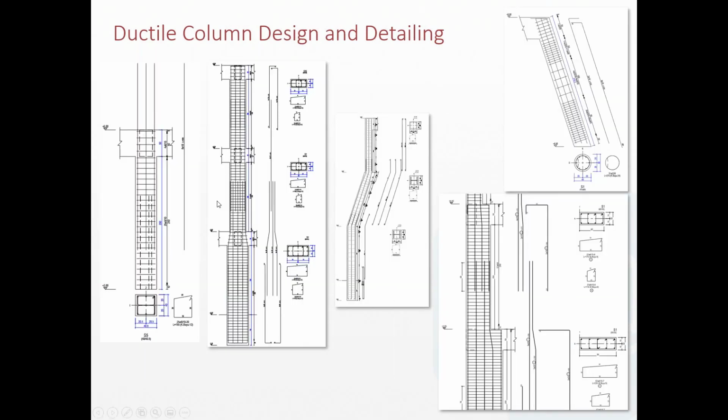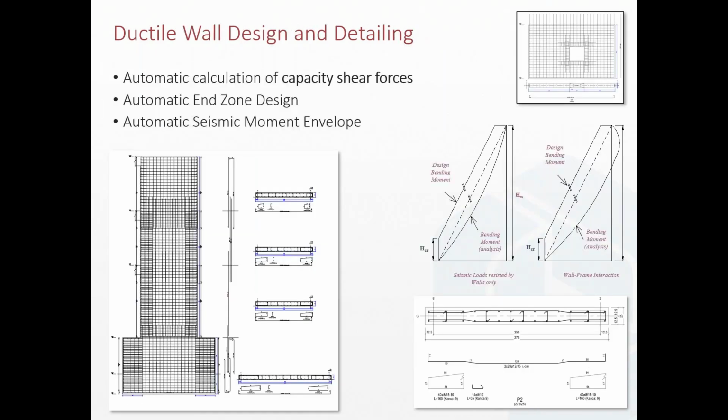Now, the column design and detailing will all be done in accordance with the ductile detailing requirements. You can see different plastic hinge zones, or confinement detailing in critical shear zones, being provided. When columns change in size and the like, the bars will adapt. If you've got bars that need to curtail because a column steps in too far, this is all automated. So these are smart things that we're doing to help with the way in which the detailing is being done. Ductile design and detailing includes the critical height zones, and designing the walls based on envelopes.